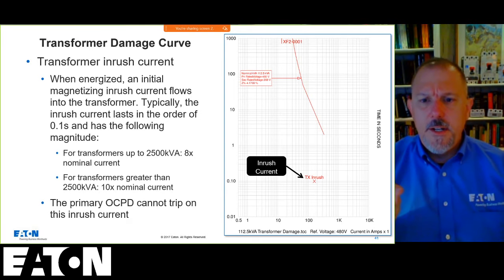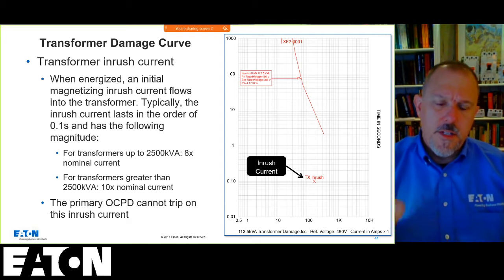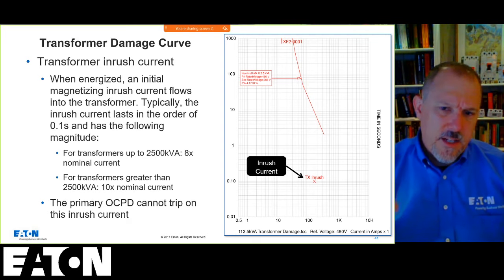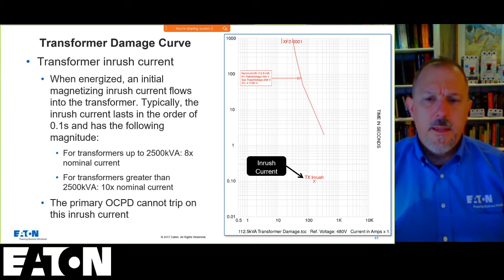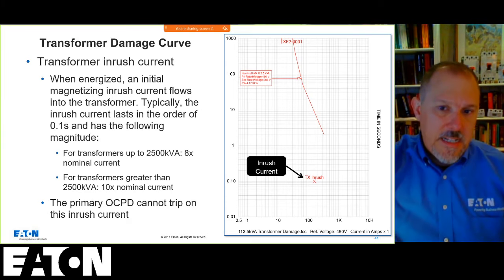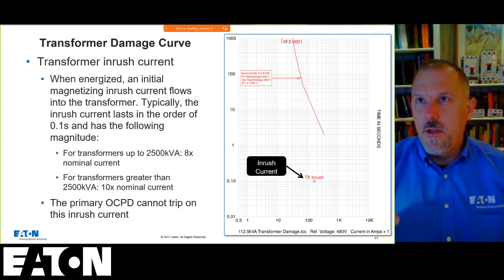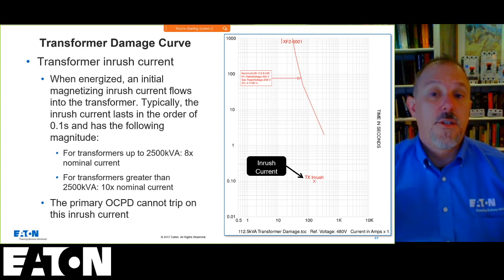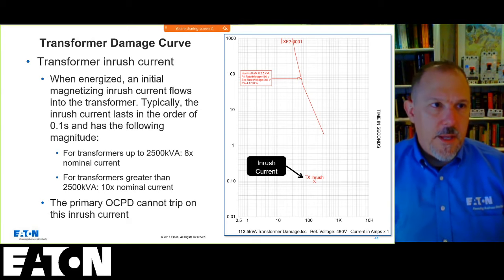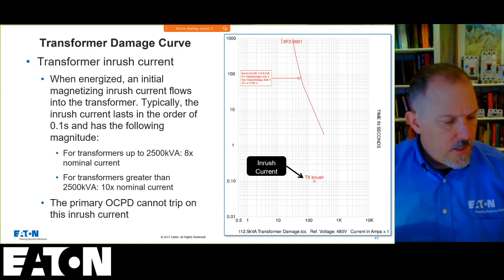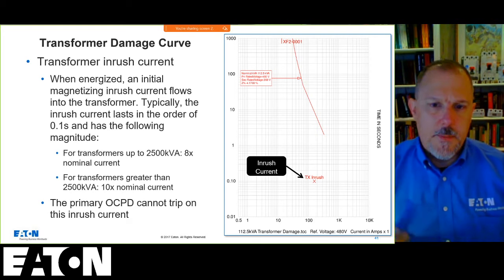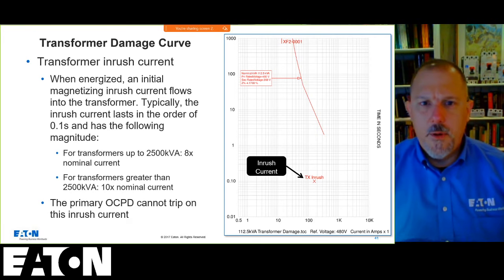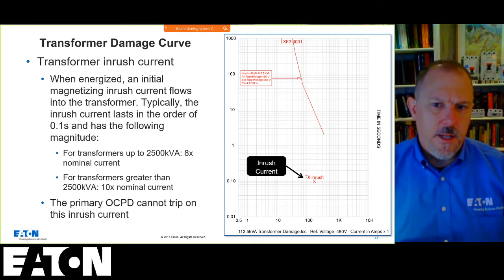I just saw a note. What's a snubber? Don Gannier. I will put some links to snubber technology. It's basically a tuned filter that takes out that high frequency, that transient voltage that will occur. And usually you get those transient voltages from fast switching. So I think you probably have more issues when you're using something like a vacuum interrupter to do switching as opposed to some other technologies. But when you're switching that transformer on and off quickly, you can create high voltages. And what we do is we create a filter that basically takes that transient out.